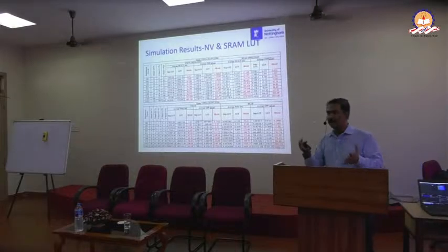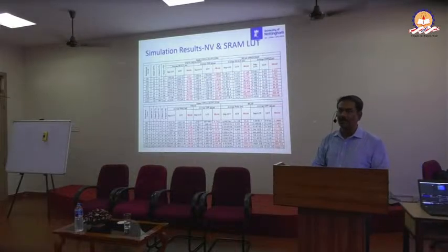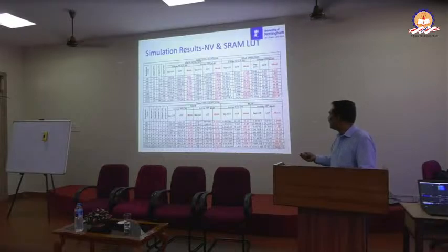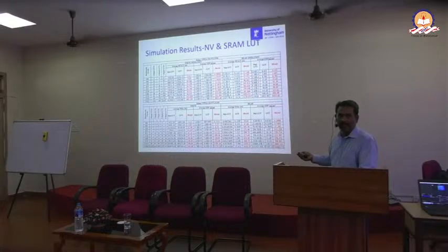We took real FPGAs, a Virtex 4 FPGA and a Virtex 5 FPGA. In both FPGAs, we implemented a lot of benchmark circuits. You can see the number of LUTs in these benchmark circuits. We implemented these benchmark circuits using our method of designing non-volatile LUTs and also using SRAM.